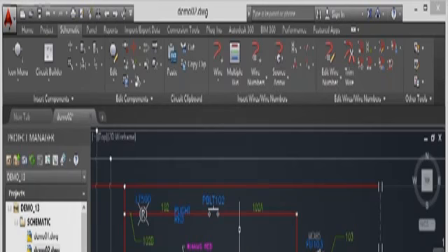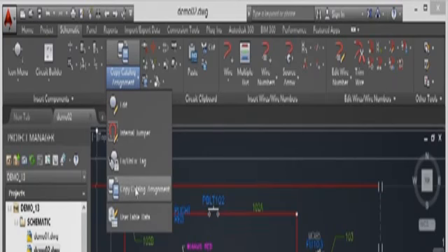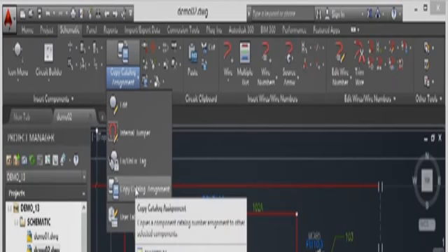You can, in AutoCAD Electrical, copy your catalog assignments from one component to another. Quite often when you insert a component from the icon menu, you'll find that there's no catalog assignment. It's not linked to a particular manufacturer's catalog, for example. It's very quick and easy to do, and again, it's on the Schematic tab here on the ribbon. What you need to do is go to the Edit Components panel and click on this flyout here. And you want to use Copy Catalog Assignment.